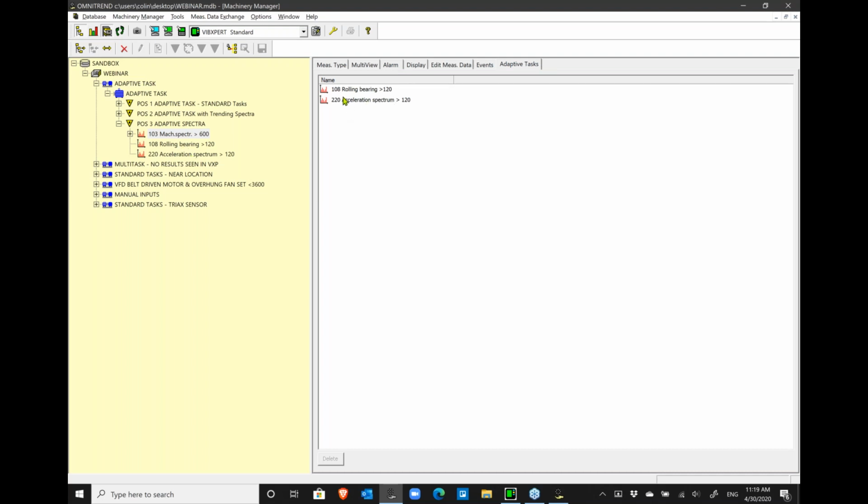I usually apply this by taking a medium frequency, or medium resolution, spectra that captures a good set of data. If there is a fault or an issue, I have it capture a good bearing envelope, if I'm not already taking one, and I have it take a high resolution spectra. So I'm not always taking the high resolution spectra; it only appears when it needs to appear. That's one way of collecting the data faster.